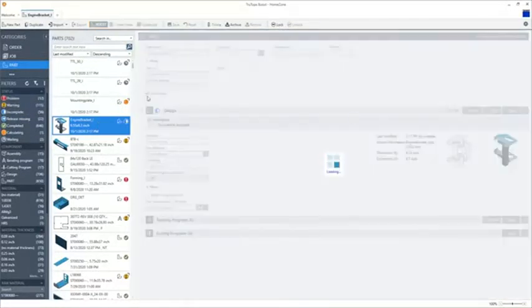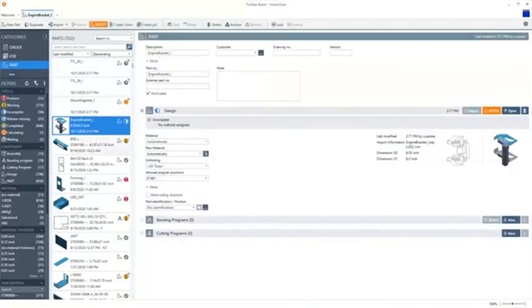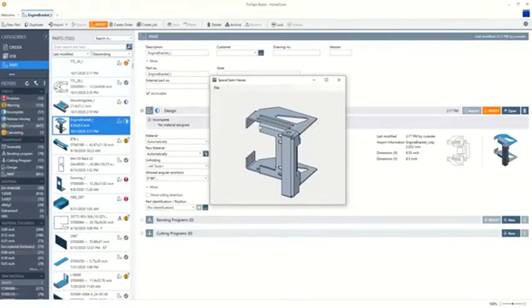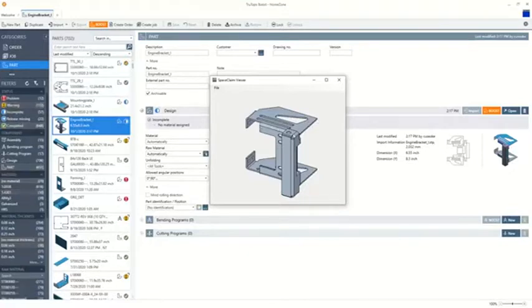So that means it's basically importing the model, it's looking at its features, and it's making sure that it's drawn from one solid, that it's one consistent thickness, that it has consistent radius values on all the flanges. There's no overlapping bodies, surfaces, faces, or problems with that model.